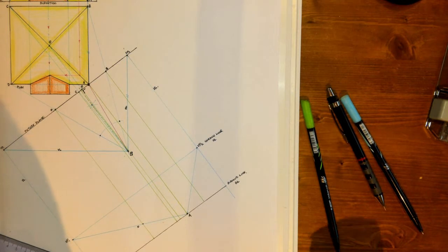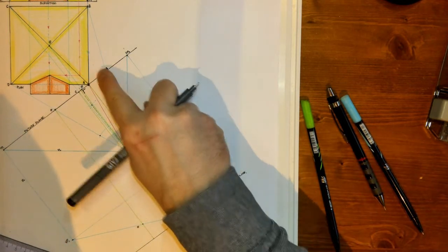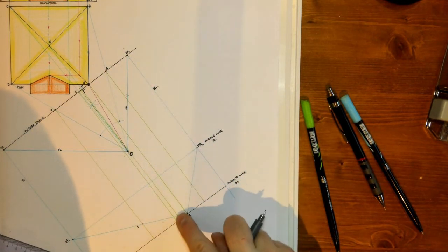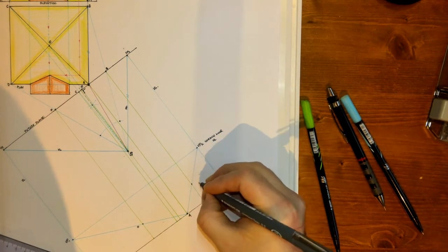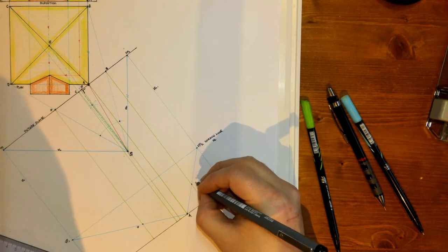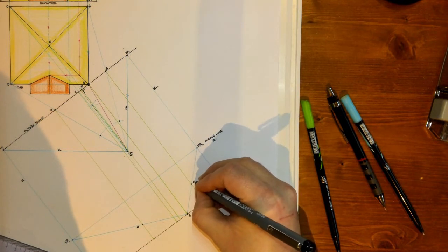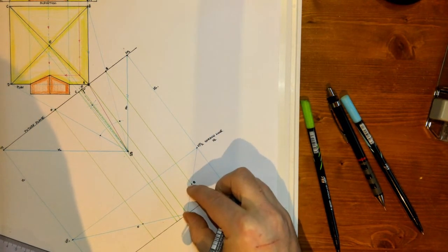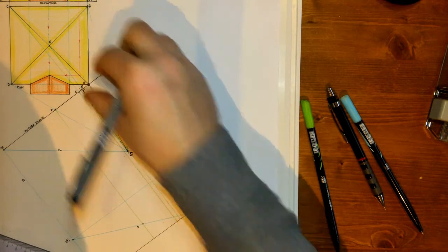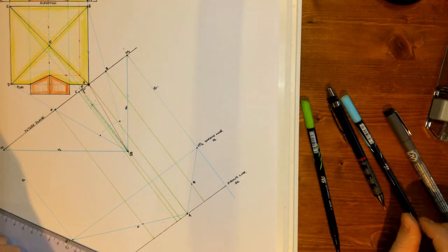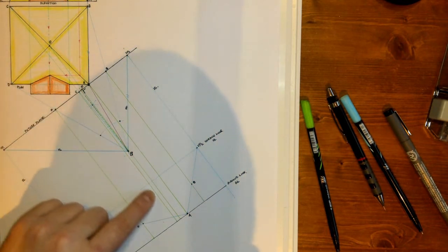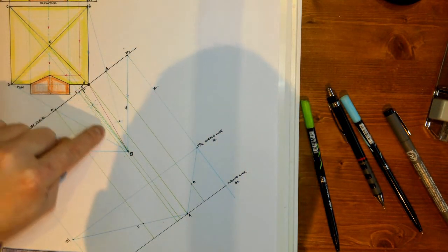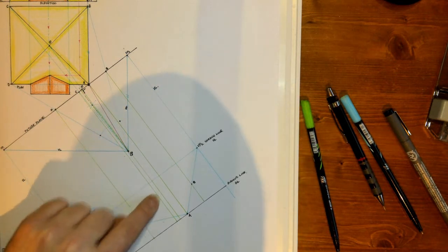So there's D right there. Okay? Now for point B, B comes down and it intersects the vanishing line going from A to VP2. So there we go. We have that line, B. Okay, and you see how much shorter it is than the actual one. It's, I mean, probably about 2/5 of the length. And then I'm going to go, well, where's point C? Well, here's the projection line for C coming down, but I don't know where to stop it.